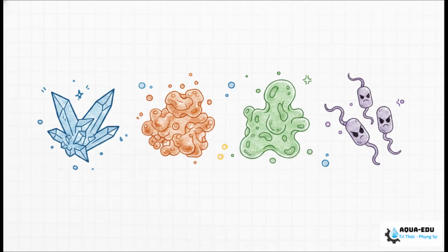What exactly is choking our system? Well, we have a pretty familiar lineup of notorious offenders. First up, hard inorganic scales like calcium carbonate or sparingly soluble sulfates, think barium and strontium. Then you've got metal oxides like iron or manganese, which will instantly precipitate the second they're oxidized. We might also be dealing with polymerized silica or even tiny colloidal deposits that manage to sneak past pre-treatment. Over on the organic side, natural organic matter like humic or fulvic acid from surface water can quickly form this thick, suffocating gel right on the membrane.